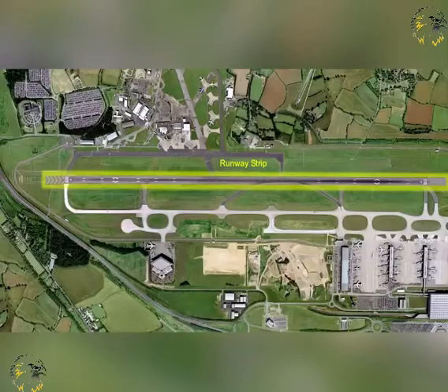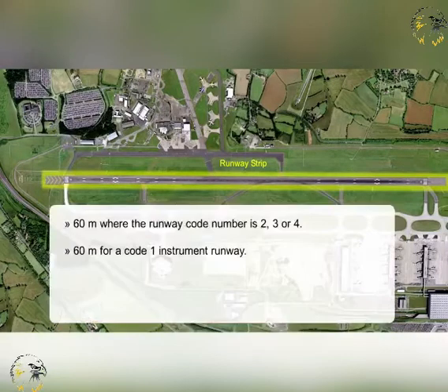A runway strip is defined as a surrounding area, including the runway, and stopway if one exists, in which obstacles are kept to a minimum. Any obstacles that are operationally necessary, lights, equipment cabins, etc., must be frangible. The purpose of a runway strip is to reduce the risk of damage to aircraft running off the runway, and to protect aircraft flying over it during takeoff or landing operations.